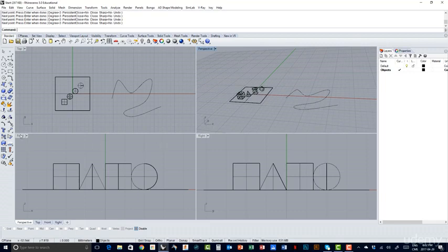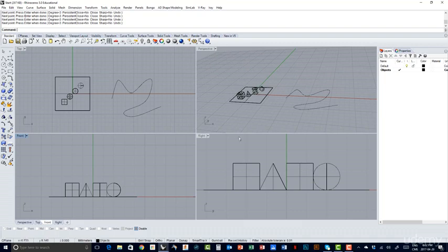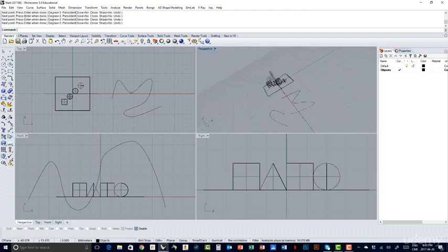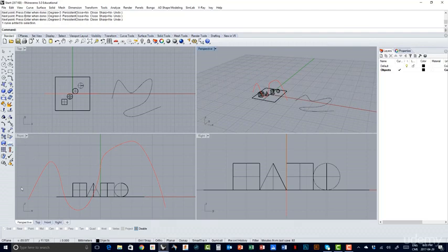On the front viewport, it's a bit different. This grid is different from what you see on the perspective grid. The perspective grid matches the one with the top viewport. So if I do a little demonstration with the front viewport, and I just want to draw a set of 2D curves like this by clicking on this icon, and I start working like this. If I look at the left-hand side corner here, you can see that I'm working on the ZX plane. The ZX plane in perspective is here, and if I rotate, I've sketched a 2D curve that is perfectly flat, as you can see here. So that matches the front viewport, ZX.